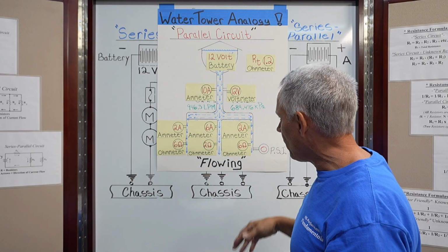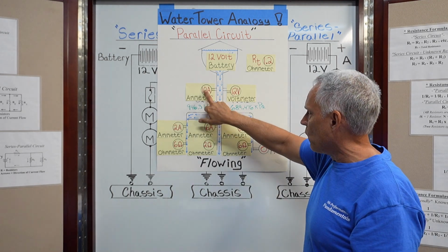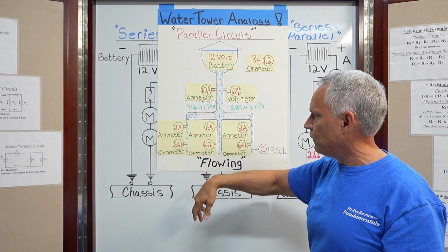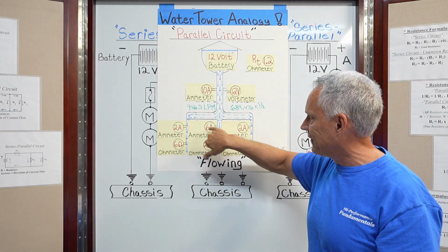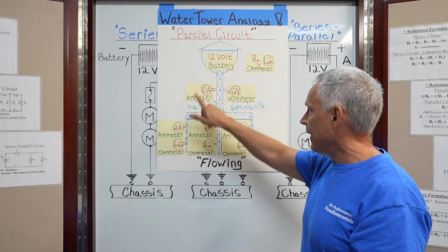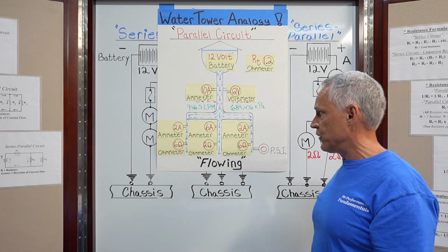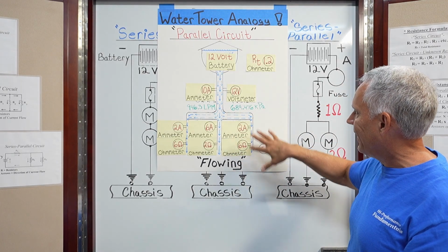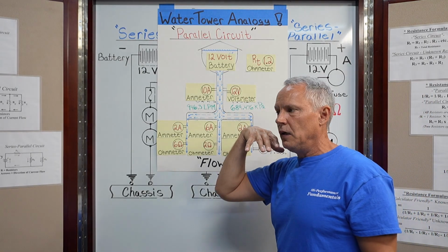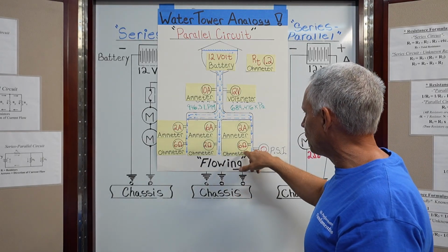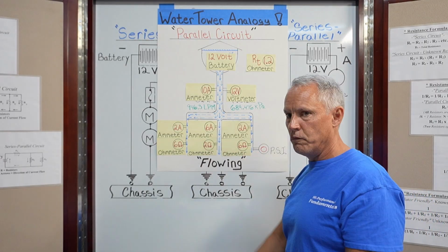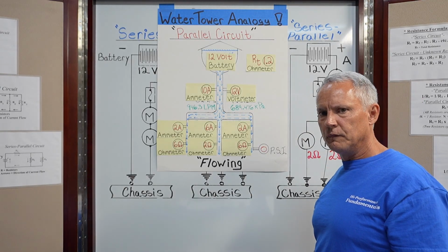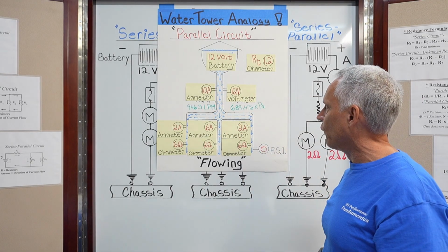All right? So, what do we know? We have 10 amps going in. This leg flows 6, this leg flows 2, this leg flows 2. Total current is 2 plus 6 plus 2, which is 10 amps, right? We now know that our calculation is accurate, right? Our resistance in the circuit, like we had shown earlier, is a parallel resistance calculation. Our lowest resistance shown is 2 ohms. Notice that the overall circuit resistance is 1.2 ohms, right? That is our calculation for this circuit, right?